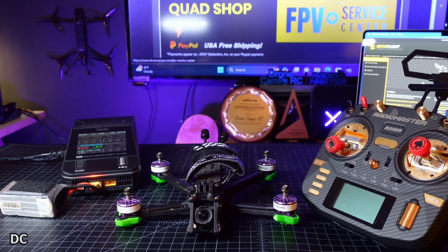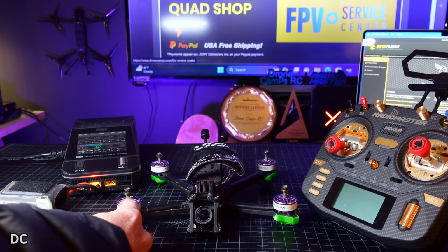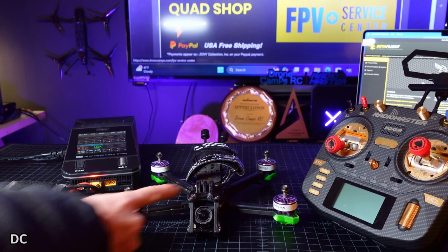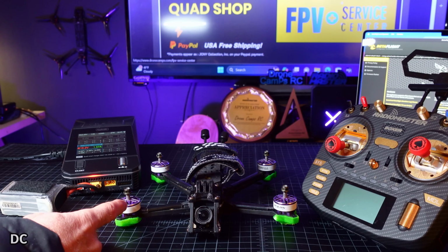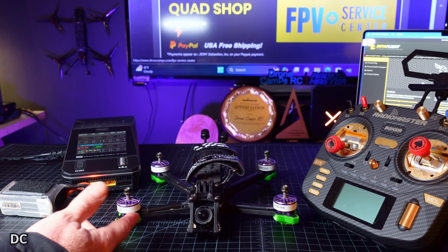And the reason that it goes so crazy and it happens so violently is because there's an odd external force that the flight controller is not ready for. And when there is a prop on wrong, it's an extreme amount of force. So what happens is it causes the flight controller to freak out.